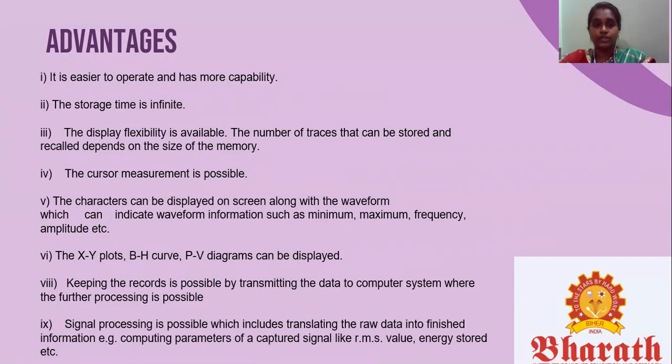Now coming to the advantages of this DSO, it is easier to operate and has more capabilities, and the storage time is infinite. Display flexibility is available. The number of traces that can be stored and recalled depends upon the size of the memory. Cursor measurement is possible. Characters can be displayed on screen along with the waveform, which can indicate waveform information such as minimum, maximum, frequency, amplitude, etc. XY plots, BH curves, and PV diagrams can also be displayed.